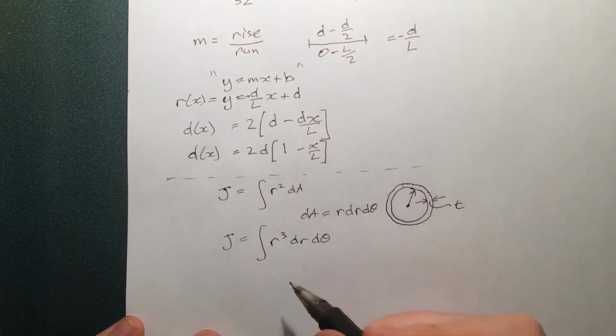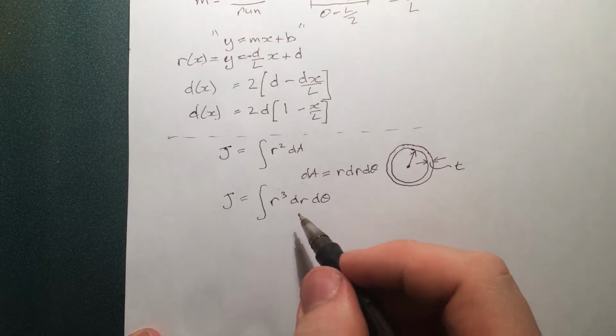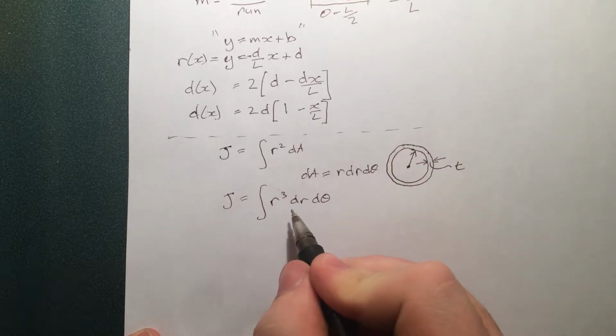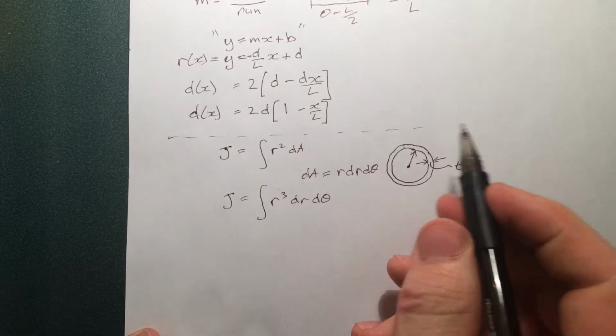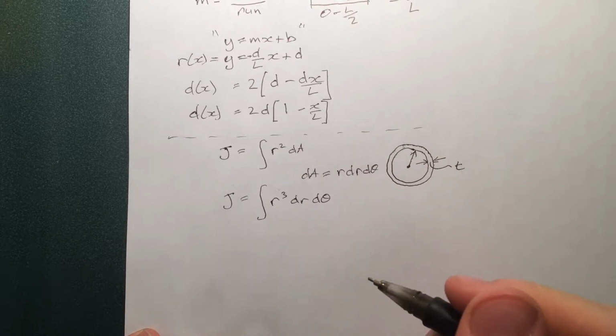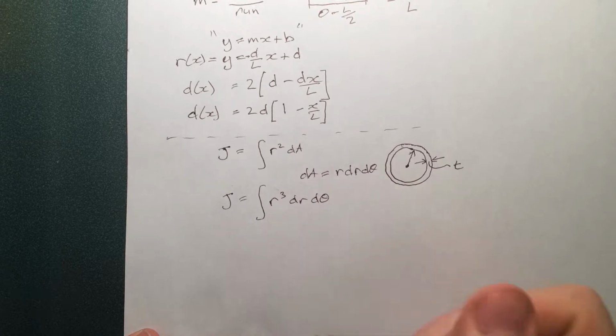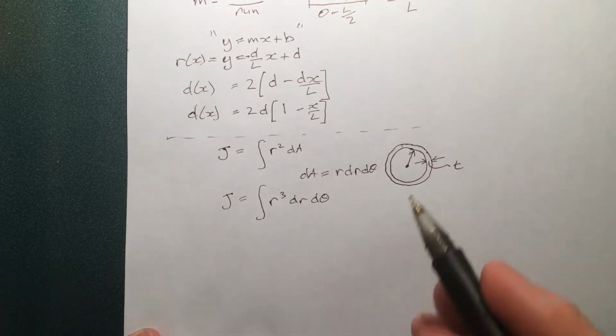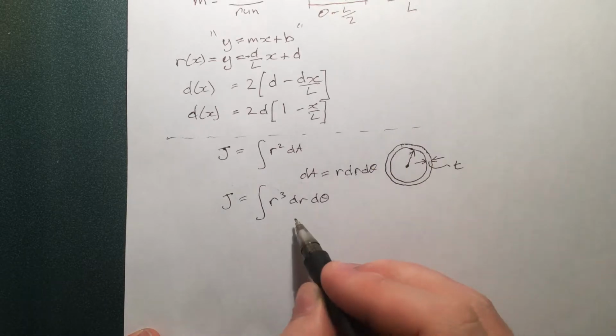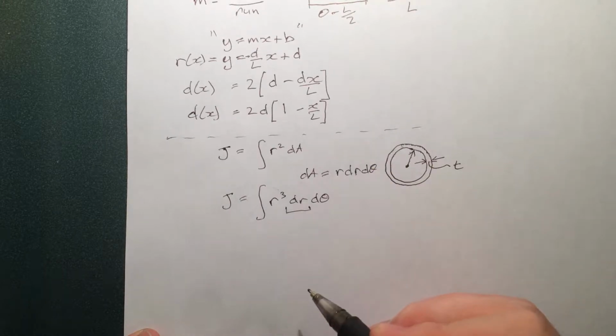Now, for a thin-walled piece, or let's just explain it slightly differently. For a thick-walled piece, we just sum up the dr from 0 to some distance r, and that would give us the r to the 4 by 4, and then the 2 pi takes care of the rest. But for a thin-walled piece, we're going to say that the thickness can be approximated by this dr, right?